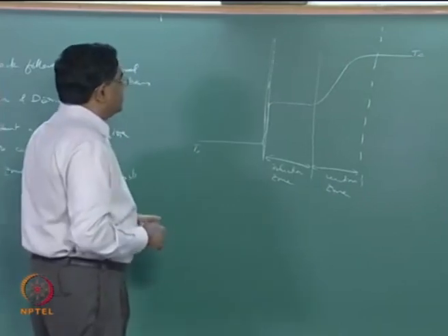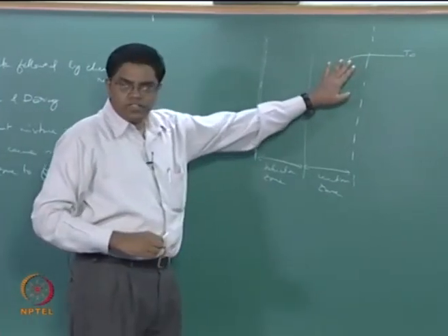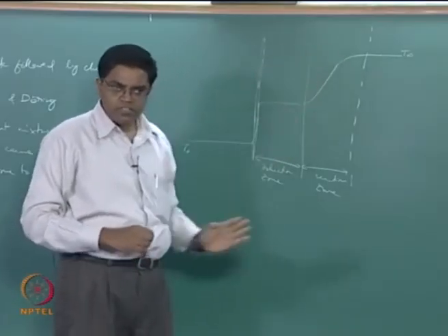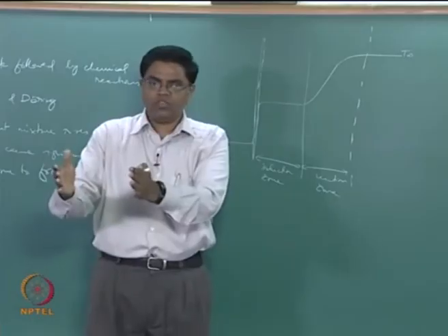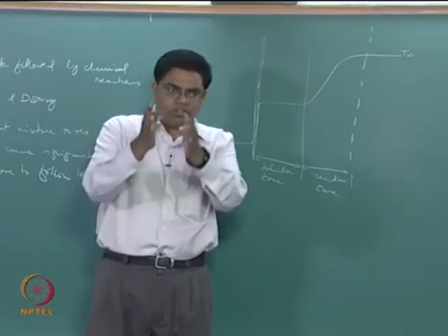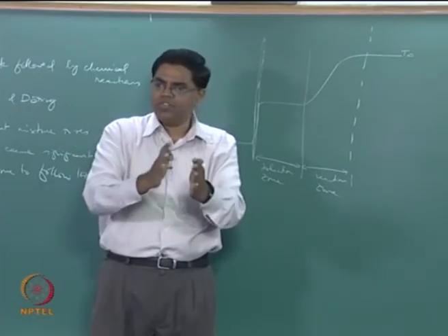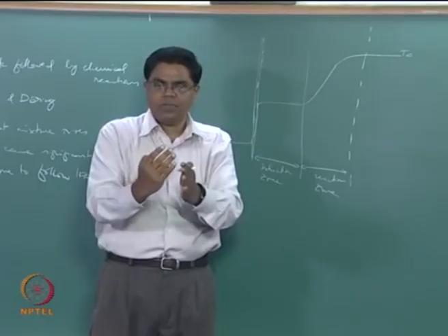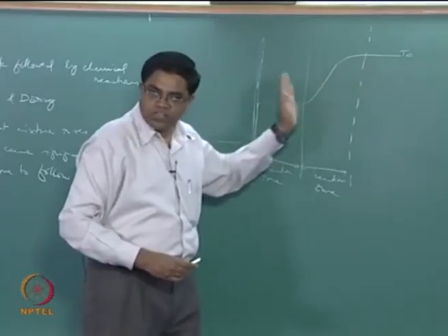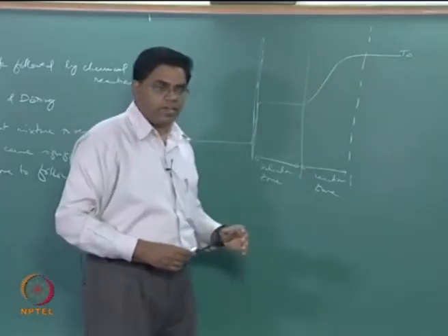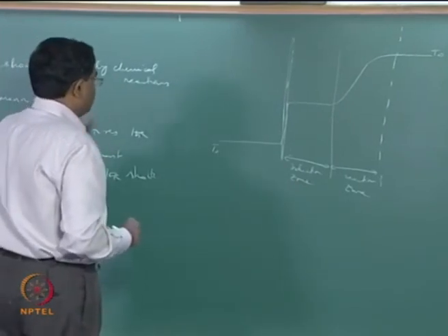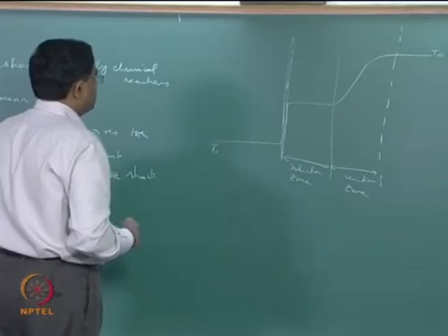and then you have this sudden rise. This rise, unlike in deflagrations, has a significant convective effect along. In the case of deflagrations we had a preheat zone which was primarily a conductive-diffusive balance with no reactive component, and then the reaction zone where you had a reactive-diffusive balance with hardly a convective effect. But here you have significant convection happening in this reaction zone as well, because you have very fast flow rates there.